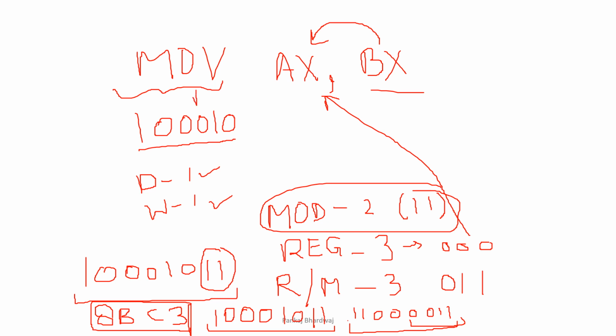You know the opcode for MOV, you know the opcodes used for AX and BX, similarly all other registers, so you can easily calculate the opcodes or the machine codes of all other instructions associated with the 8086 microprocessor.